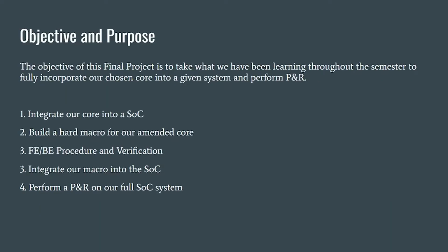The objective of this final project is to take what we have been learning throughout the semester to fully incorporate our chosen core into a given system and perform PNR. To do so, we first have to adjust our core so that it fits into our system on chip. Then, we'll build a hard macro for our amended core, which we can then use in the front and back end procedure and verification. Then, we integrate our macro into the system on chip, and finally perform a PNR on our full system on chip system.